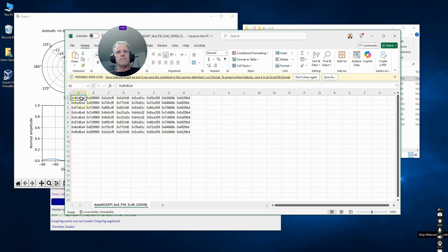This is the control word, the first two MSBs. This is the amplitude settings, and these here are the phase settings for the array that you want to configure, for example, in an 8 by 8 configuration.